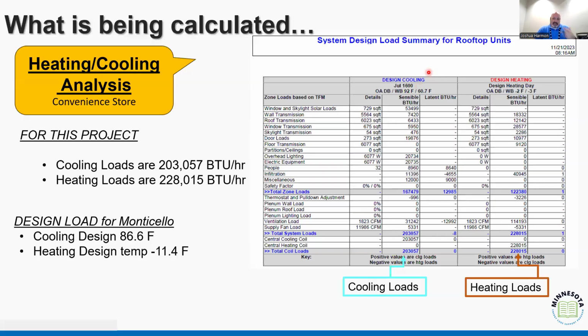And so I'm supposed to design a system that's capable of meeting that need, right? Based on the building that I own, the building I'm designing. And so overall, that's how we get to this calculation, right? The sensible load. Remember, sensible load is what we're using to change the temperature. Latent is what's going on in the room, right? These are people in the building put off this much heat and cooling, right?